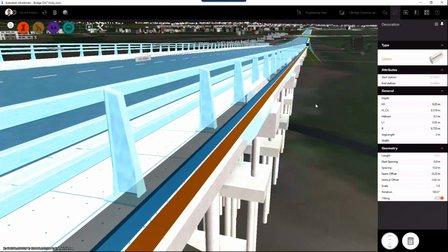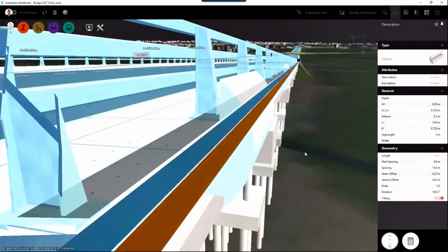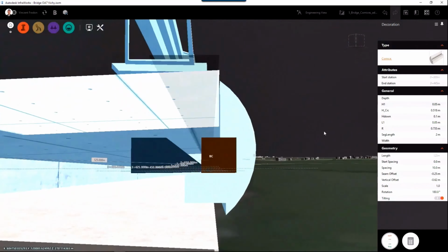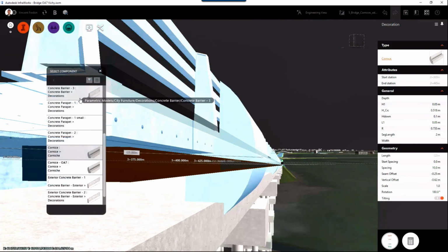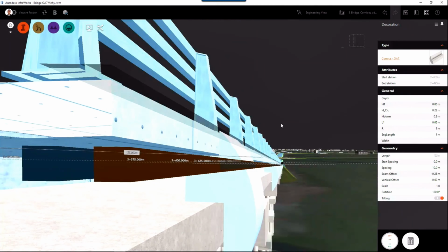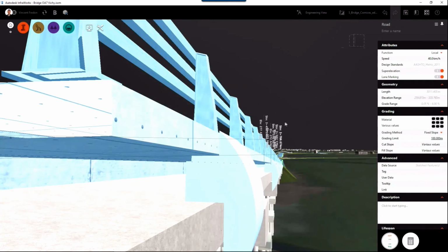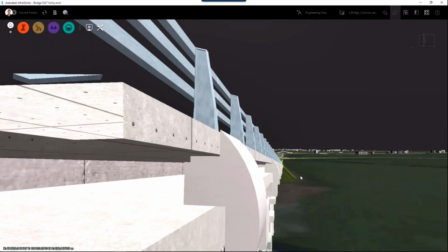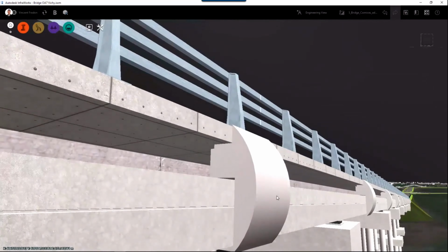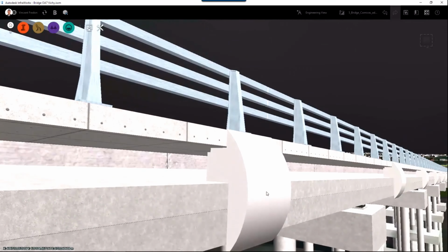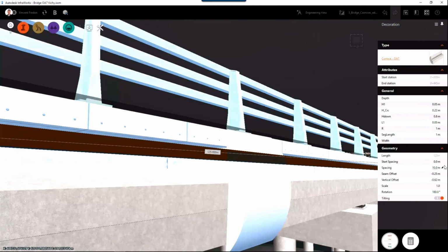I will change the model. As Stephane said, when you import a 3D model from Inventor in InfraWorks, you can set different presets for each model. And here, I've created a specific preset for this bridge to have a better adaptation of this cornice model to this bridge.